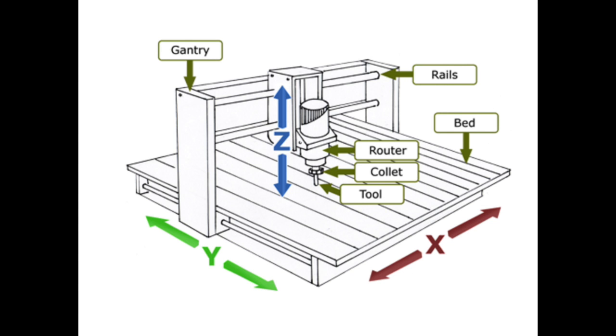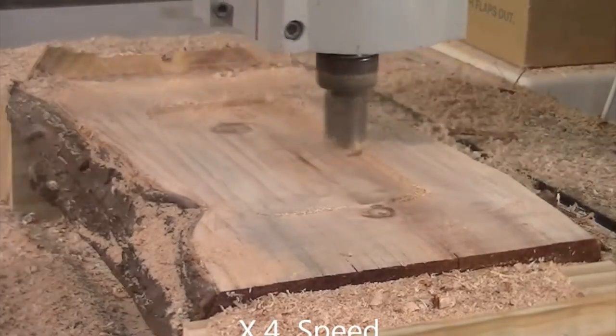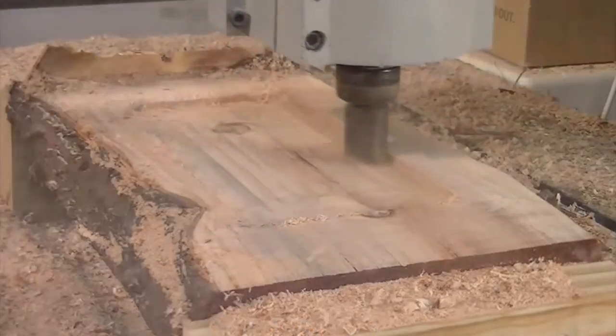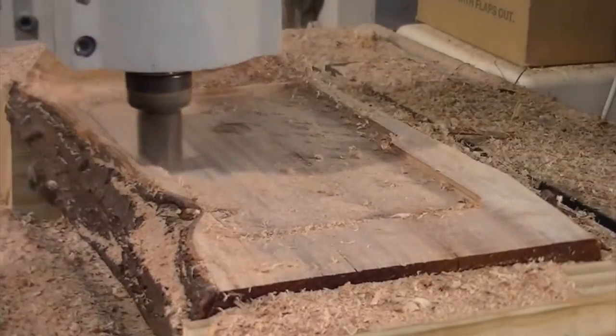For those who don't know, CNC stands for Computer Numeric Controlled and is a form of digital fabrication that allows you to carve or cut a computer-generated shape out of a material. A mill or router in the CNC machine works kind of like a drill, but it's so powerful that the machine can be dragged over a material to cut it away layer by layer.